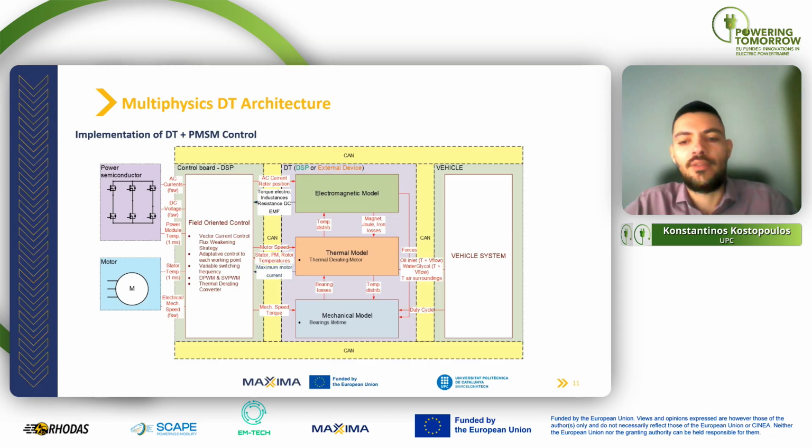So we have a feedback loop between the control board, the motor, and the digital twin. And everything communicates using the CAN-bus communication protocol. And this is not just a simulation running in parallel. This is a closed-loop control system where physics-based predictions actively optimize the real-time motor operation.